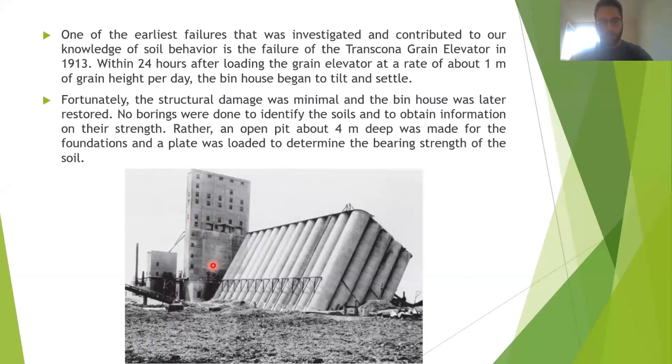Usually, you need to look in the standards and norms from your country. But in the European Union, we have something called Eurocode 7, and Eurocode 7 defines the minimum investigation you will have on site. The minimal investigation for buildings is one borehole in a square of 15 x 15 meters, and that borehole needs to be 3 times the width of the foundation that's going to be there.